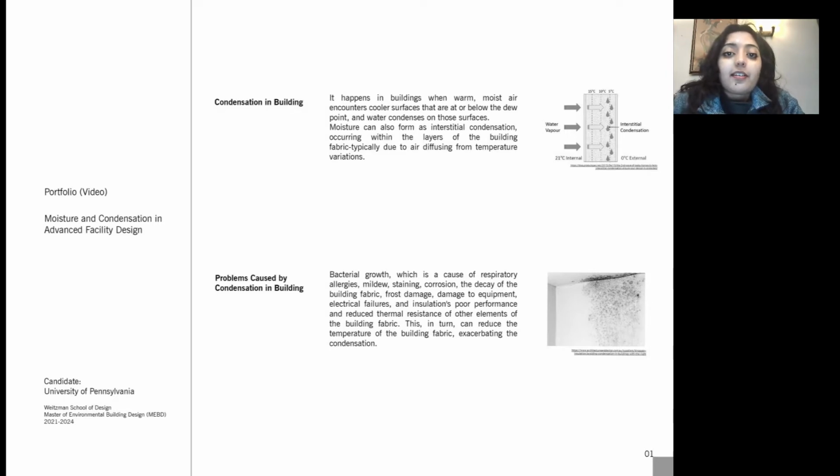Biotech and API facilities with sterile areas are constantly working towards methods to mitigate the problem pertaining to moisture and temperature control. Within the building exterior wall, there will be a point where air diffuses from the building's warm interior to the cool exterior and reaches its dew point within the construction of the building itself, turning water vapors into droplets. This is called interstitial condensation.